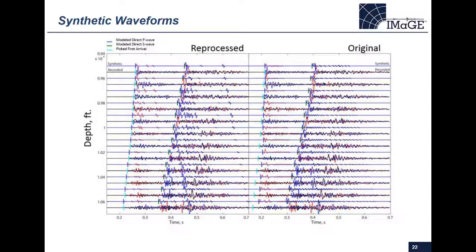This has also helped us identify that there's a bit of a head wave or refracted wave in the recorded data. So you can see probably the direct wave is this larger P arrival coming later, but there is a bit of a signal beforehand, which is sometimes hard to pick up and is actually a refracted wave that our software is trying to locate.